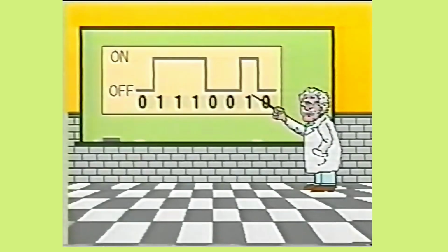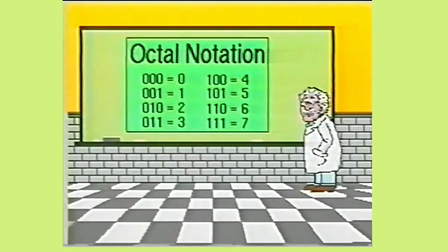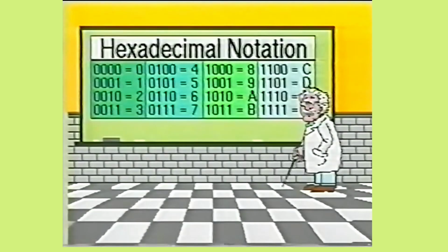Digital circuits operate with the binary system due to its simplicity in having only 2 states of energy, on and off. To simplify the calculations of large binary numbers, 2 common notation groups of bits are used, octal and hexadecimal. The octal system uses a base of 8 and only utilizes digits 0 through 7. The hexadecimal system, on the other hand, uses a base of 16 and uses digits 0 through 9 and letters A through F.